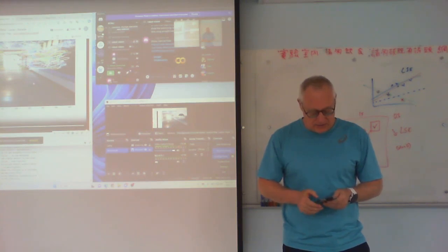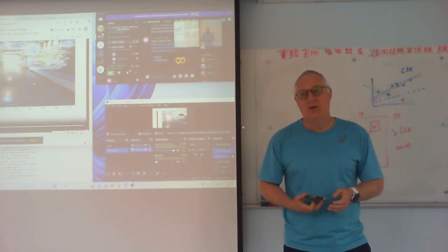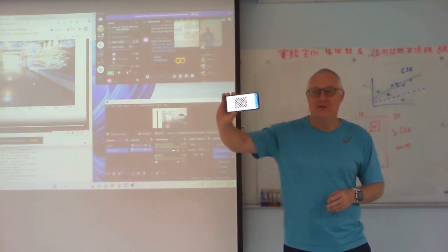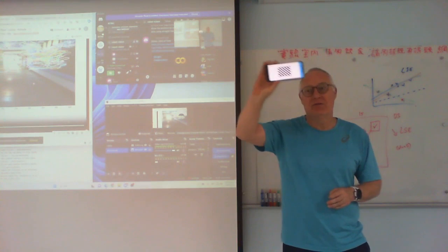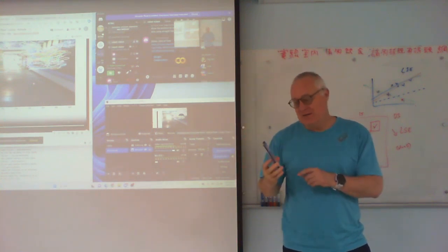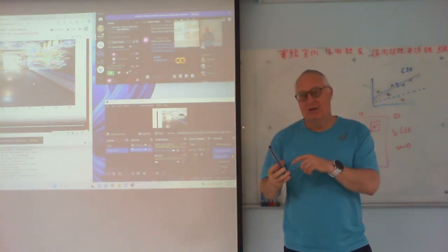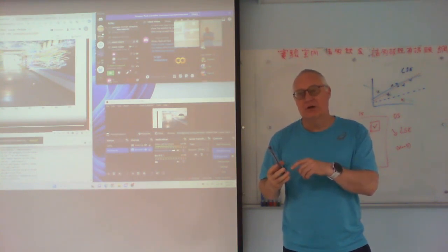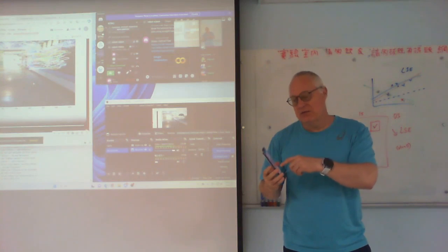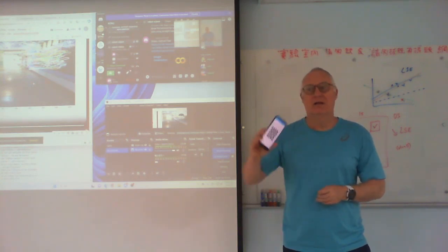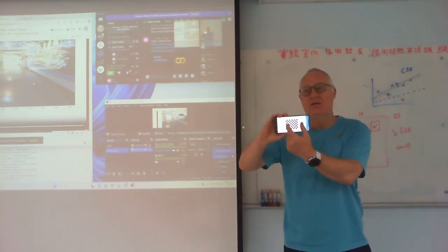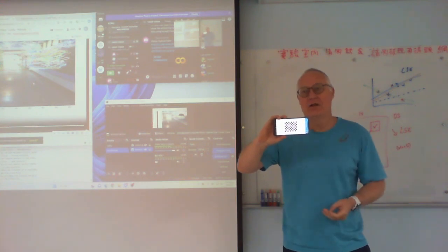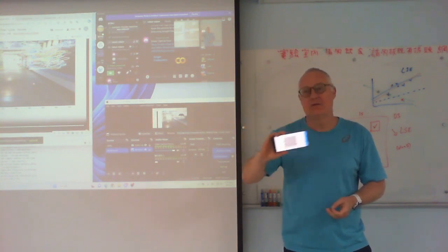I'm trying with the checkerboard, and I'm wasting a lot of time. So I wrote the thing so that I can just use the phone. I hold it up in front of the camera, and the web server runs on the robot. So I connect to the robot, it sends me the picture, and when it can actually see the pattern, it can vary the sizes of these things so that it gets a good match, and then you just have to wave it around a couple of times.